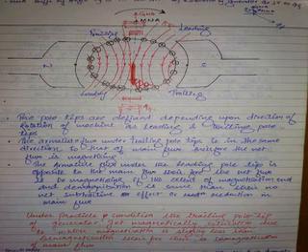So now, in the third diagram, we will consider the main flux as well as armature flux. For your understanding, we consider them differently. In the first figure, you consider only main flux. In the second figure, you consider only armature flux. You won't get only armature flux without main flux. When main flux cuts the conductors, voltage is induced. You are loading it, current flows. So, to understand how exactly the armature flux is, you consider it separately. But practically, what will be there in the machine? There is main flux, there is armature flux simultaneously in the air gap.